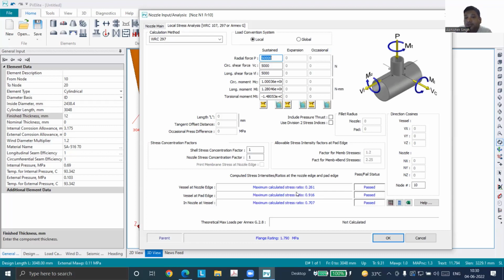So if something hits your nozzle, maybe during transportation or installation, it may immediately break. It will be very weak. So just to strengthen the smaller 2-inch nozzles, which are very fragile, we provide stiffeners, two of them, 90 degrees apart. That is the standard.